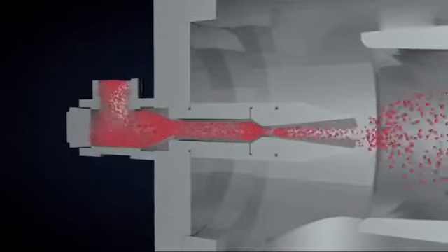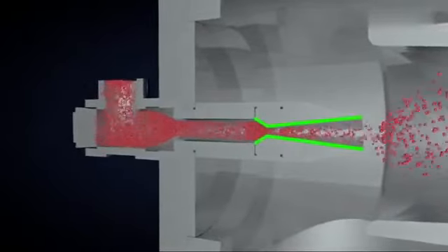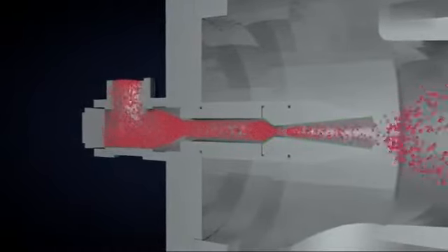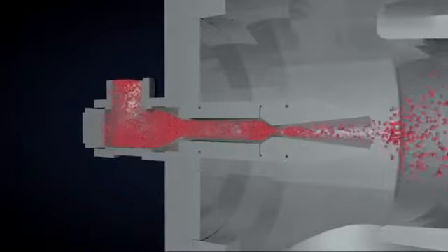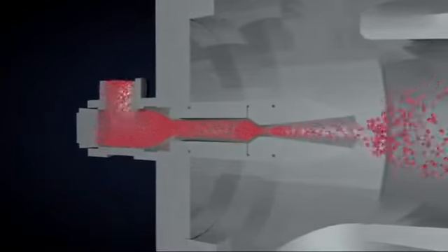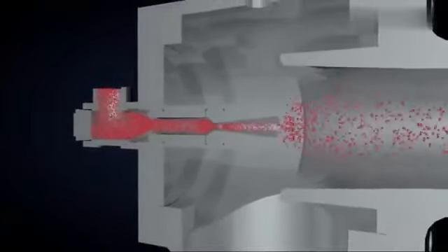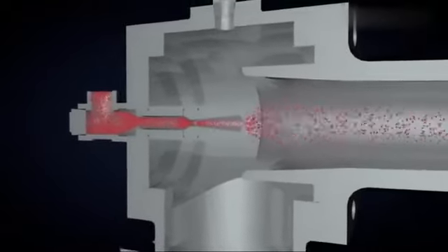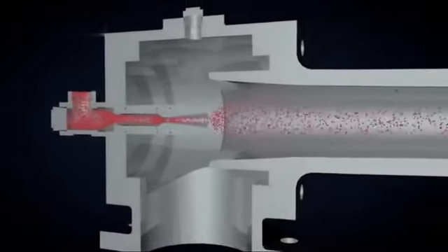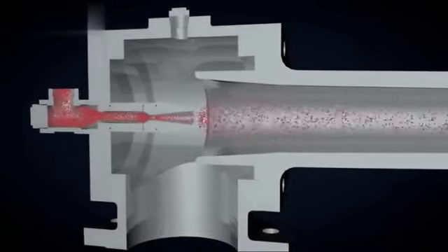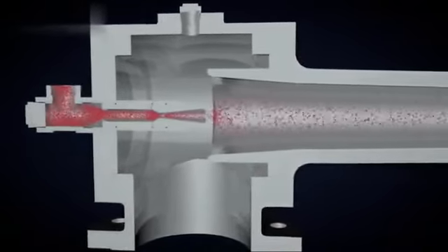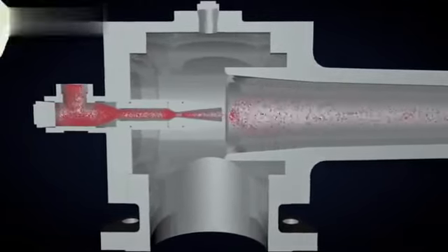The second component is the motive nozzle. Once the motive steam enters the motive chest, it expands adiabatically across the converging-diverging motive nozzle, converting pressure to velocity. The pressure differential across the motive nozzle accelerates the motive fluid as it rushes to the lower pressure region of the suction chamber. A well-designed converging-diverging nozzle efficiently converts high-pressure motive to a high-velocity stream, leaving the divergent section of the nozzle. The motive gas actually expands to a pressure slightly less than the suction load pressure. That creates a localized low-pressure region, which draws in the suction load vapor.